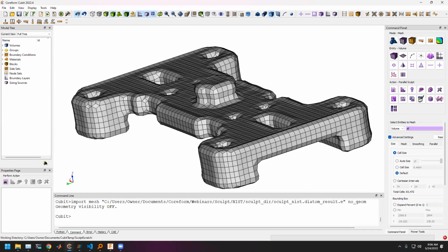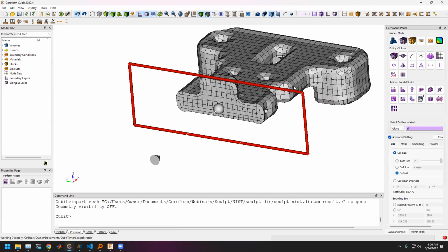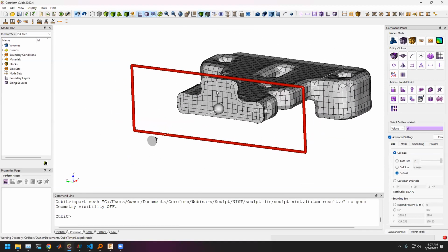But then the second aspect is that if we were to do a cut through the middle, from a finite element standpoint, one of the things we'll see is that the bounding box produces high quality elements on the interior and tends to have lower quality elements near the exterior or near the surfaces. And so oftentimes in nonlinear analyses, we actually want the highest quality elements at the boundary as opposed to on the interior, since the boundary is where things like contact and the largest deformations exist.